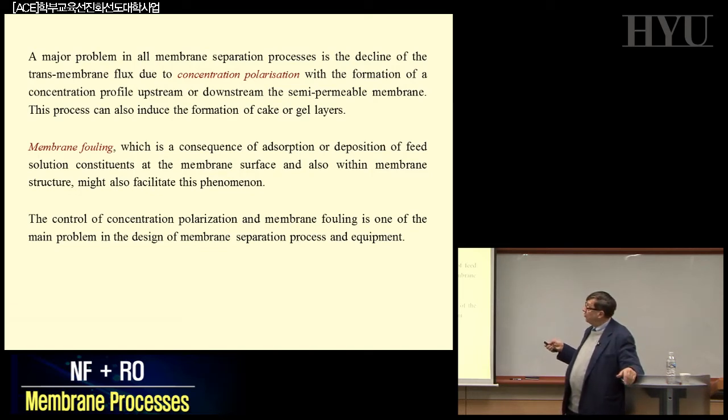That means concentration polarization, as we saw before, is increasing the concentration at the interface. Now, this increase in the concentration of the solutes present in the solution at the interface can be at the origin of fouling. You can have increased concentration, so you are increasing adsorption. You can arrive at a point where, as the concentration increases, you approach saturation and you have a change of phase. Some of the solids precipitate on the membrane surface: scaling. All these problems are present.